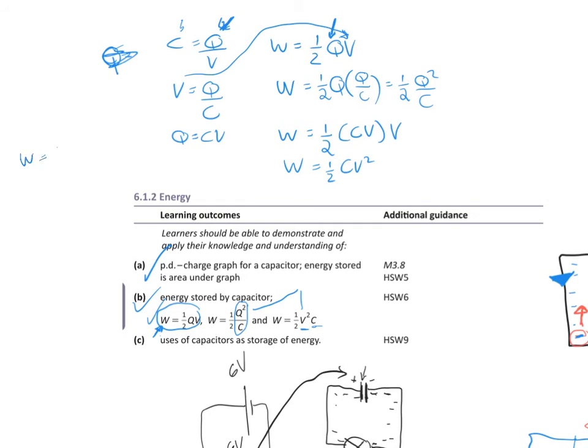So your capacitor stored 1 joule of energy. Now, if you release that energy in a flash, in a fraction of a second, say 1 millisecond, the power output is much bigger than if it took 1 second. I'll show that. Power is the rate at which energy is being transferred, so work done divided by time. That means you have 1 joule divided by 0.001, which gives you 1,000 watts, or a kilowatt.